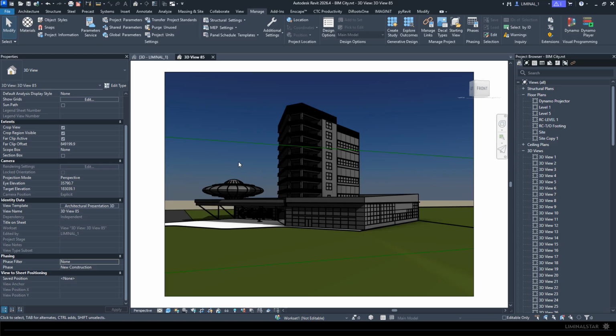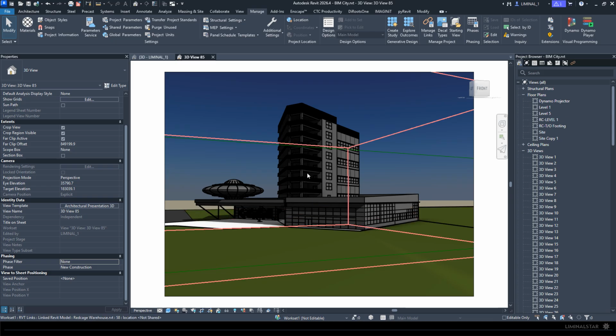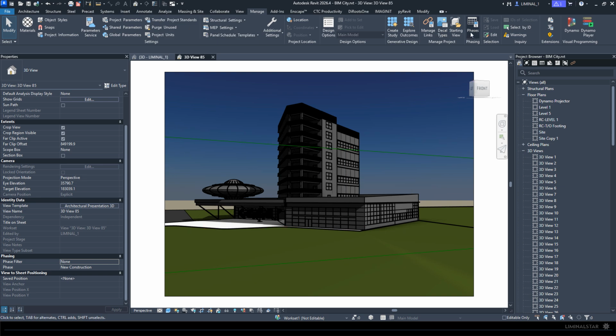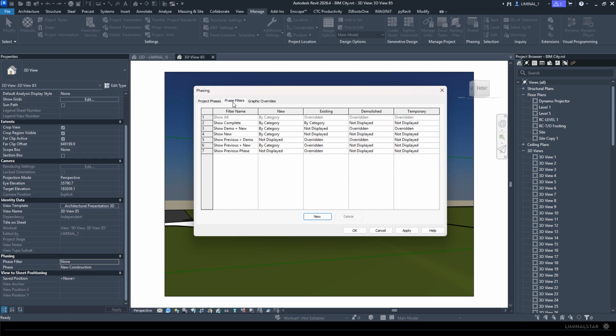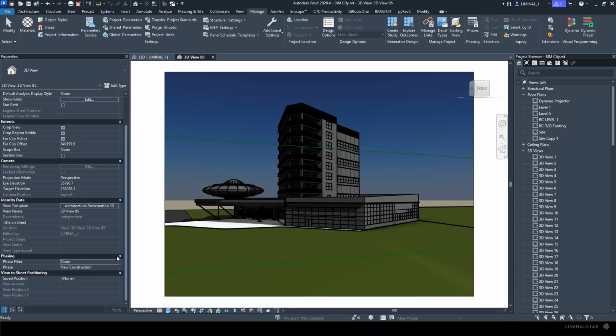So what do I have to do? Create a new one here, possibly. Let's call it conceptual new. Now for this one, we'll say show override. Anything happen here? Okay, so now what you can see is the actual topography that's in this model is showing with a halftone and a black outline.